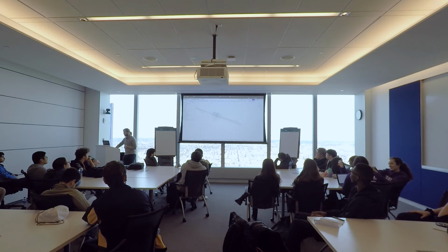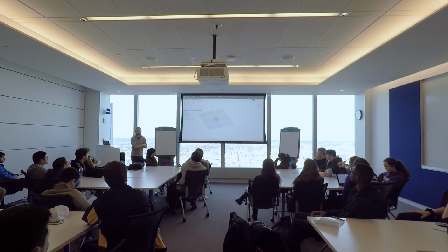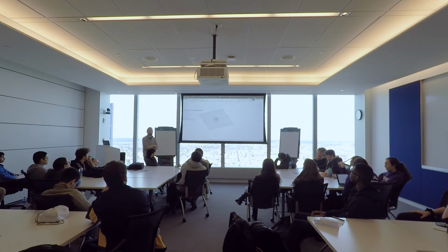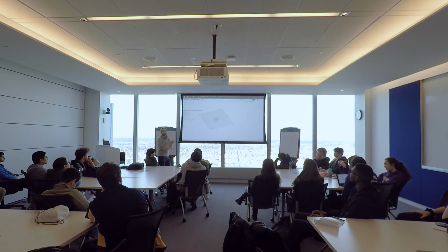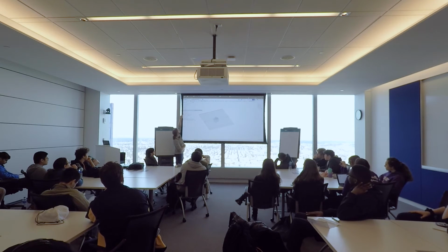So the other thing that I really didn't talk about a whole lot is variables. I use variables a lot in CAD, especially during the early part of the season when you don't know exactly what size your robot might be, when you're still making decisions on that. Here you'll see I have a variable for wheel diameter. I have the base length, the base width. I have the center drop defined in here.